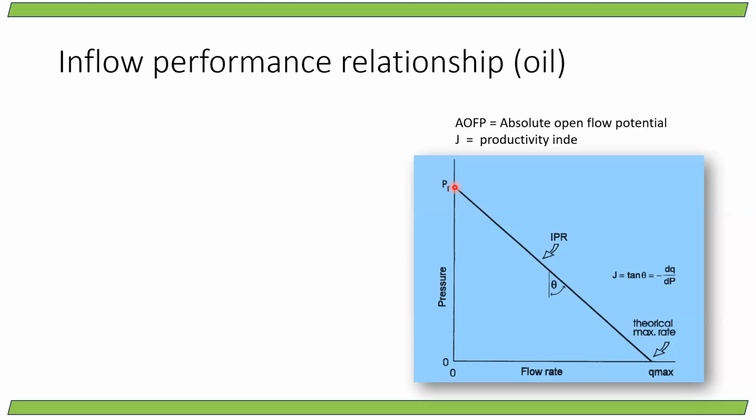A little lower will help a healthy way of producing oil, but a drastic drop may exceed what your well has the capacity to exploit. Why? Because the volume is huge and the tubing size is limited, so you cannot produce with that difference in real time. But theoretically, when the wellbore pressure comes close to zero, the maximum production can be expected. But it differs from one well to another, depending on parameters such as tubing sizing, choke diameters, choke pressure, flow rate, and the reservoir permeability near it. So many things impact IPR, which we are going to see further.